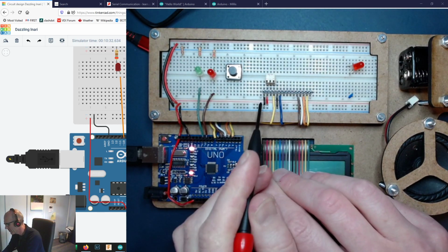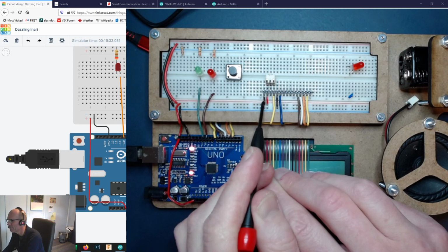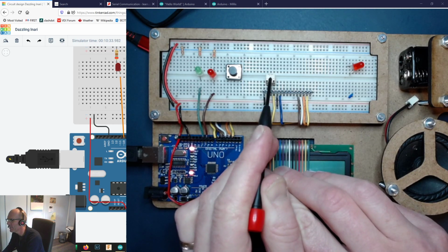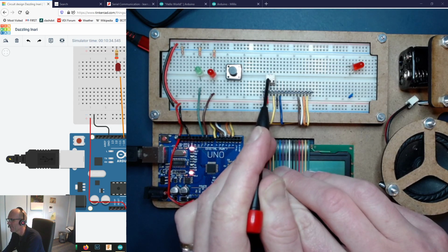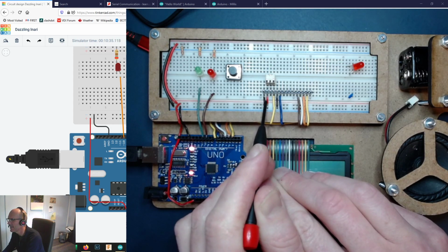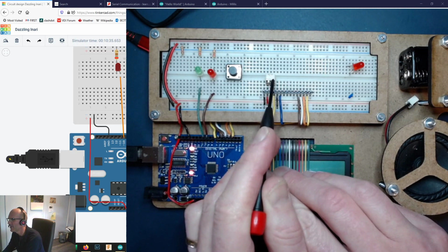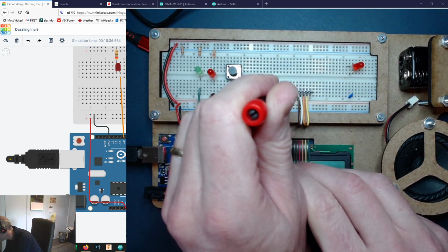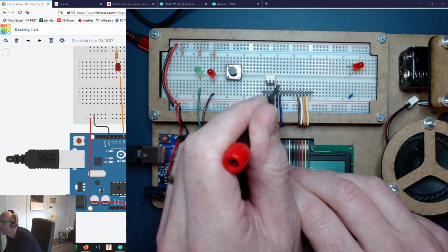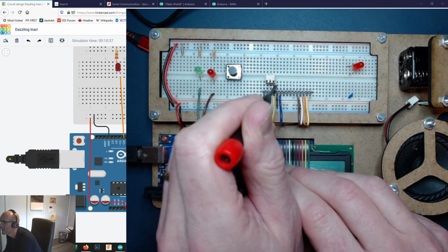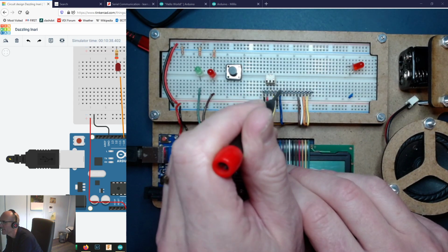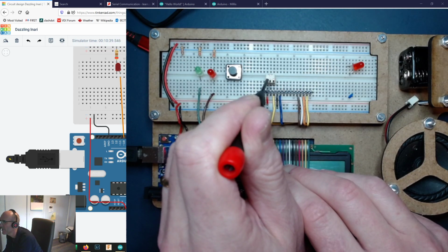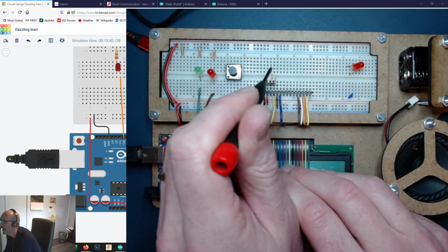So anyway, when you're looking at this, you should go black, red, and then a space right here because that will be the middle pin of your potentiometer. And one side of your potentiometer will be tied into the red side right here. One side right here has that little extra bend in the leg, so it's actually tied in right here. Okay, so you can see there's a bend on the leg. It comes across, comes in here, so it ties into the ground. So the potentiometer is split between +5 and ground right here.